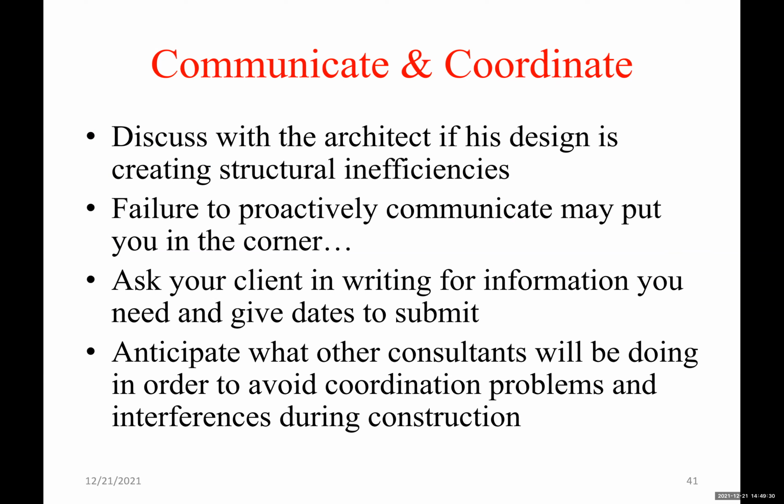Communicate and coordinate. Discuss with the architect if his design is creating structural inefficiencies. Okay, so you are the engineer, you are doing the design, and if there are any issues that the structure will be inefficient in certain locations of the building, discuss that with the architect early on before getting into shop drawings, or even erection or fabrication, things like that. Failure to proactively communicate may put you in the corner.